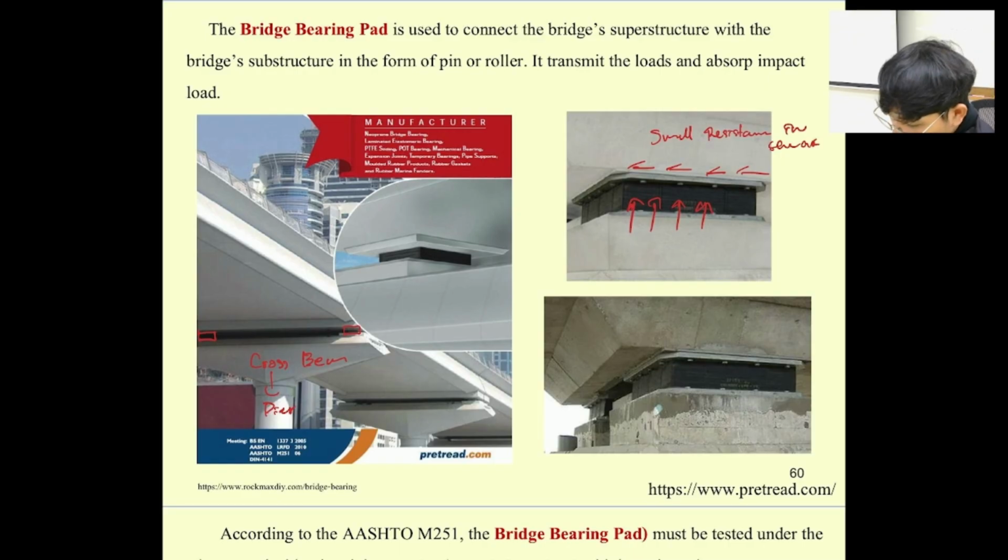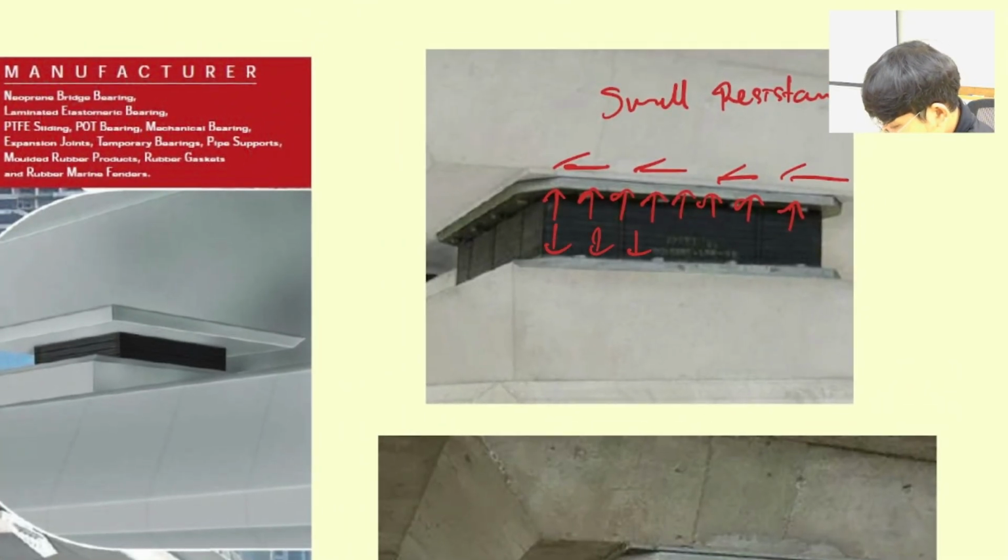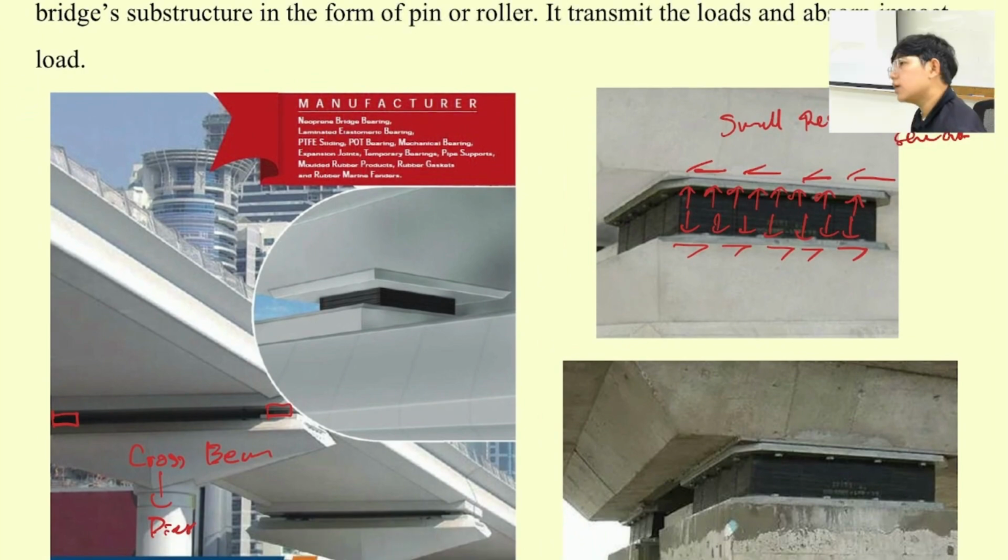Okay. Theoretically, it's going to resist the vertical load only, which is the force in one direction. Like this. We zoom in. Like this. Yes. Okay, transfer back to the cross beam, and we have shear resistance like this. But in reality, when you brake, it's going to produce some shear stress to the bearing pad, and the bearing pad still resists the axial load.